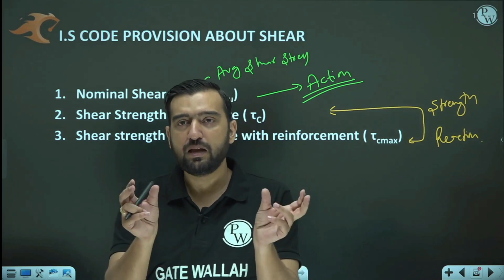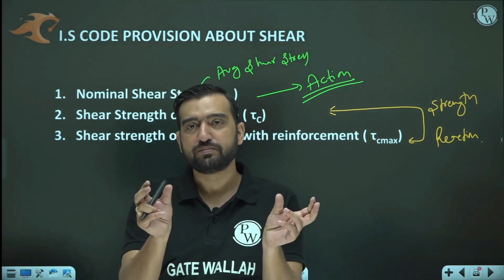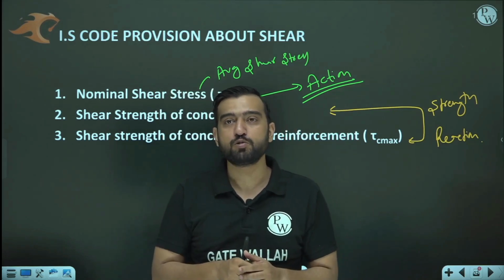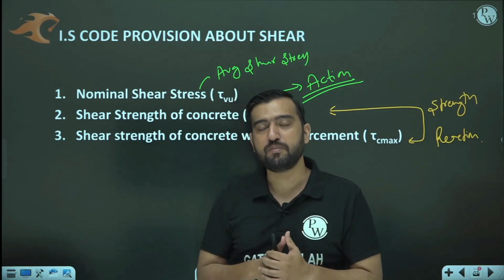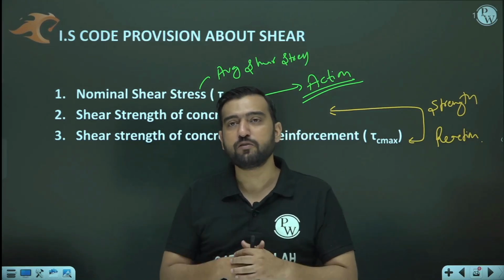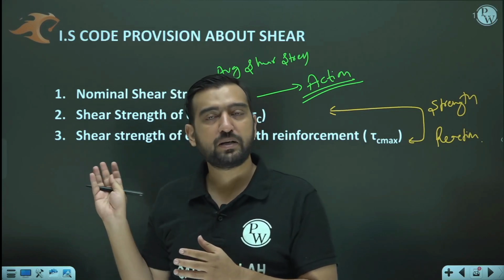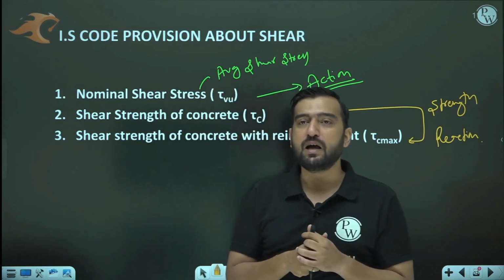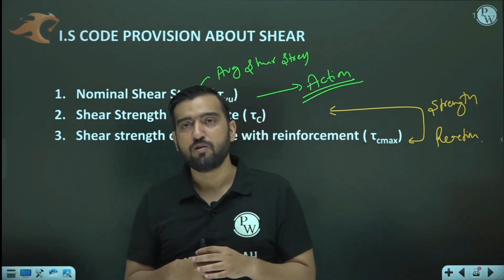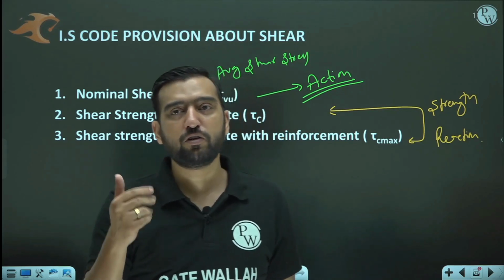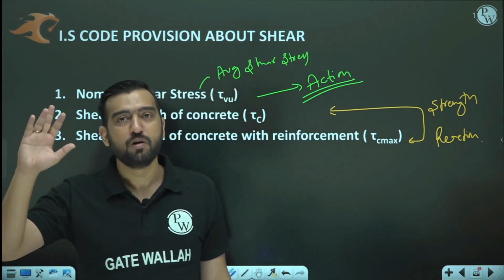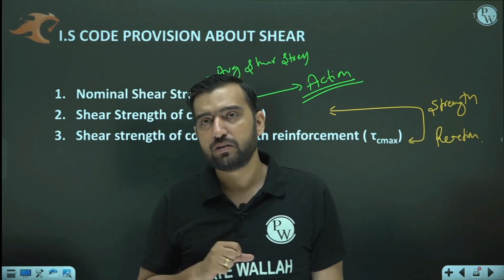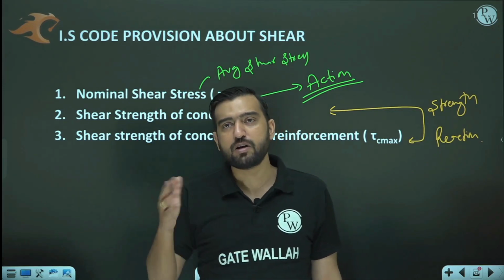And if that value is greater than the upper limit, then the situation is very critical, just like the beam here. So maybe some extreme steps you have to take. But in shear strength we are not going to design for that particular problem. We are going to revise our section, because we know that nominal shear stress is V over BD. We cannot tell our client to reduce the value of shear force. We cannot design for a particular thing for a particular force. Then what alternatives do we have?